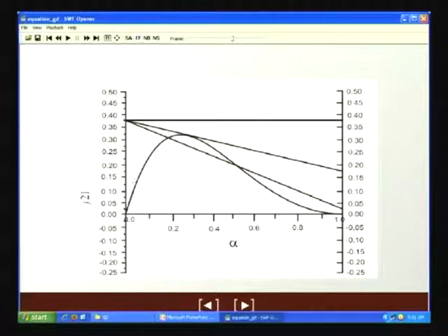Do you get the point? For each particular alpha, there will be one set of J2 and J1 under which flooding will occur. So, for each alpha, if we get J2 and J1, then we can locate each and every point, isn't it? We will find out J2, we will find out minus J1, and then at that particular alpha, the point of intersection of this alpha with the straight line will give us one particular point on the curve. Thus, from the flooding data for different values of alpha, we can locate different points on this particular curve.